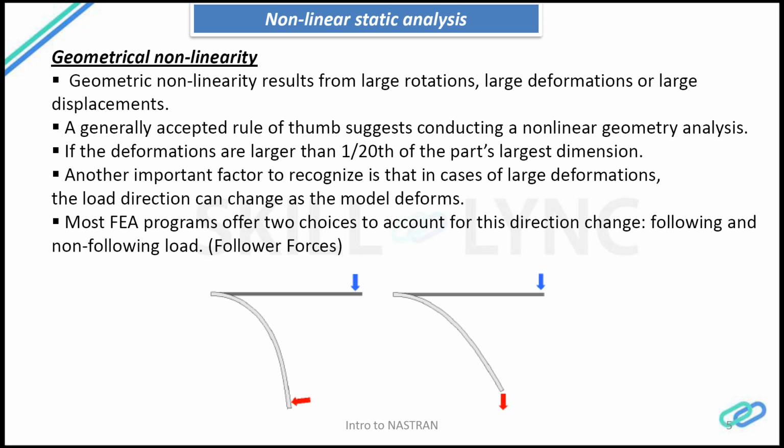Most commercially available FEA tools offer a few options while running the analysis, that is, generating follower forces or not. What it means is that if the direction of the load changes depending on the part and assembly design, it will generate follower forces. If not, then it is a non-following load.